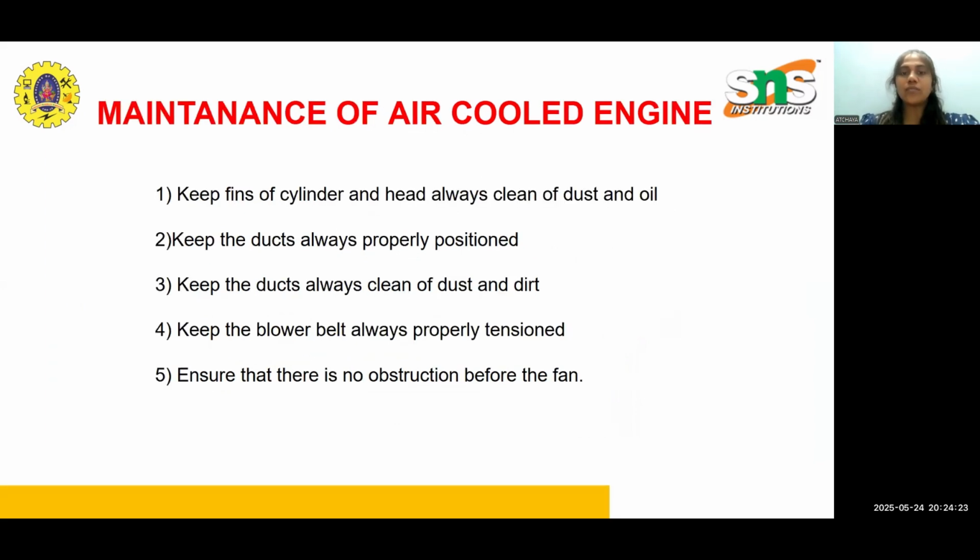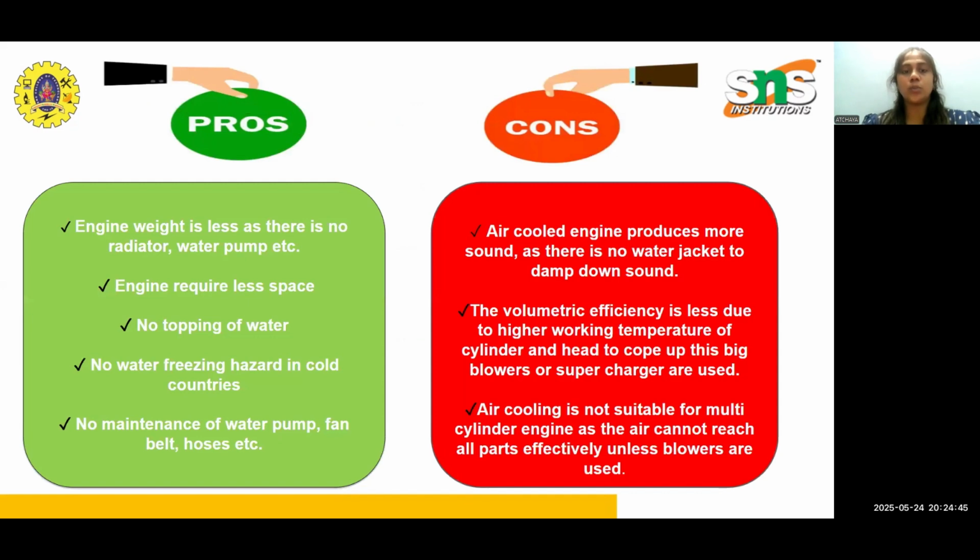The maintenance of air-cooled engine. As we all know, the fins should be dust and oil free, and the duct should always be properly positioned, and the duct should also be clean. And we have to keep the blower belt always proper, and no obstruction should be provided.